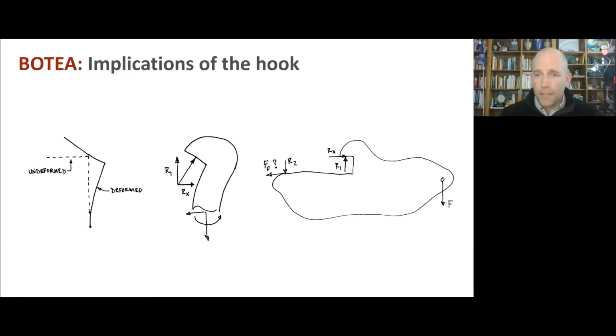And we saw lots of our designs ran into this issue: as some load was applied, eventually the component would fly off the table, and it isn't broken, it just slips off. So what can we do about this? If we really understand why this is happening now, that it's about this deformation due to bending changing the nature of the contact force between the hook and the top of the table, maybe that can give us a trick for keeping this thing from slipping off.